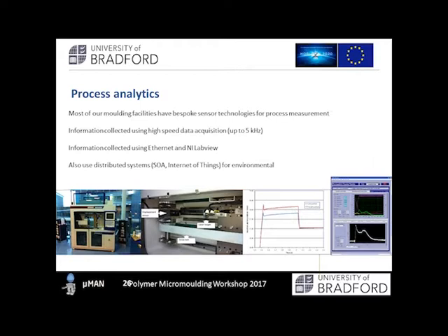But the problem is, the encoder is mounted down here on the main drive unit, but then we've got this belt system that's actually transferring that motion to the injection piston to give us the injection. So we've got this disconnect between where we could measure from and what the piston is actually doing. And when we compare the outcomes of those two measurements, we do see this slight deviation here, which is